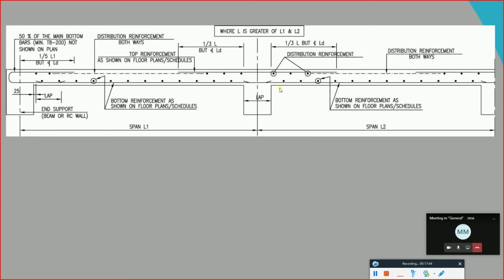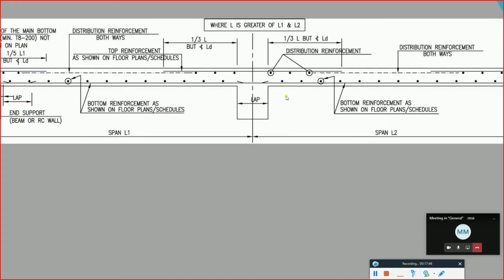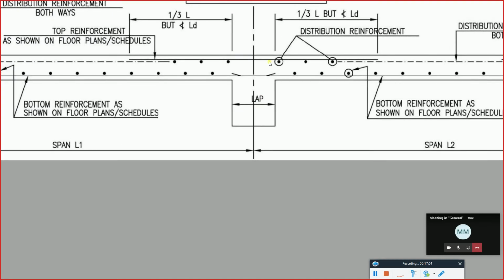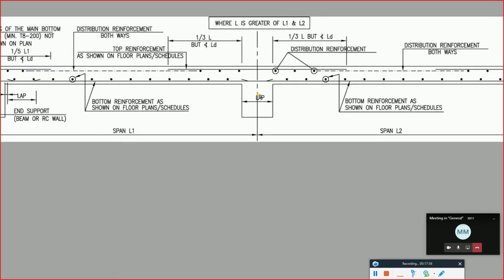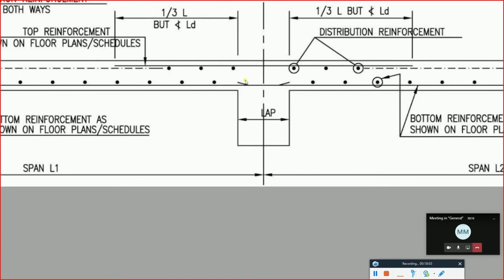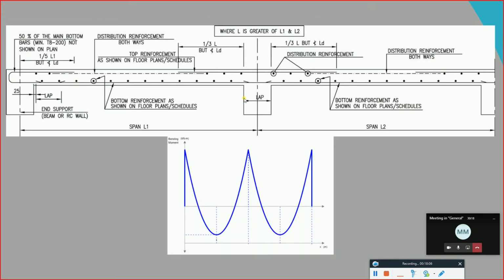So in this particular support, we need to understand that there is a support. The support will go from where to where exactly. There is a support, but we need to know the reinforcement will go from where to where exactly. So this is going to be my support. First thing, I'll be making the reinforcement. Since it's a support, if we go and see the bending moment diagram, we can see here that we have a negative bending moment. That's why, even if it's a discontinuous case, we supply a fixing or a connection reinforcement here.